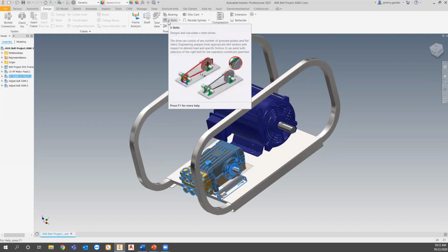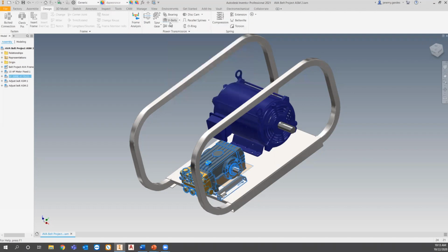Yep, and that takes care of the tensioning question that caused the error before, where it's going to use that approximate size belt for that distance. Well, in this case, you'll be able to get it perfect because it'll just throw that pulley into a location where you get the correct tension on the belt. Yeah.